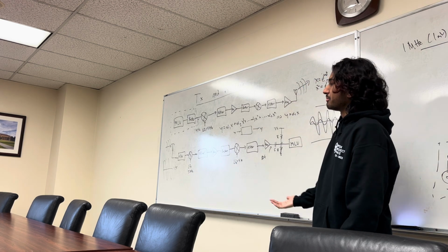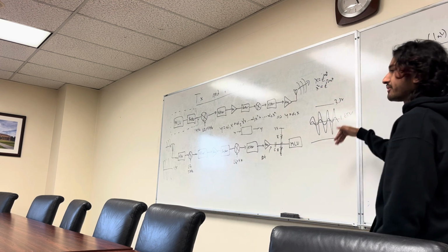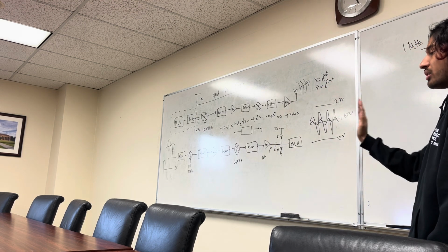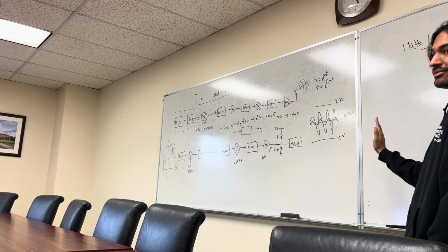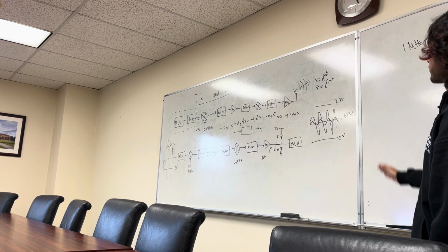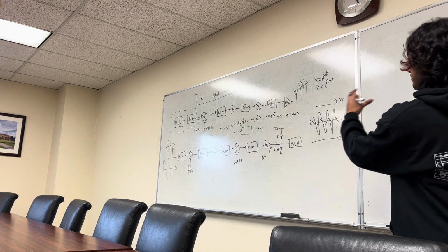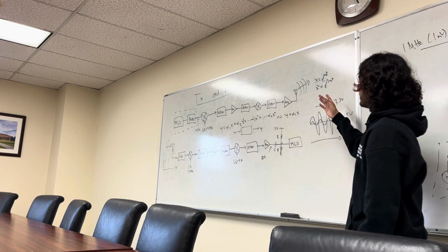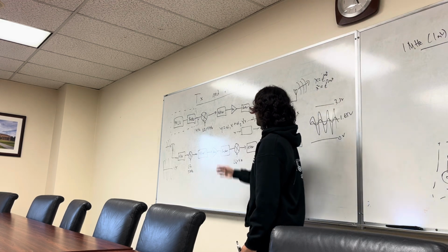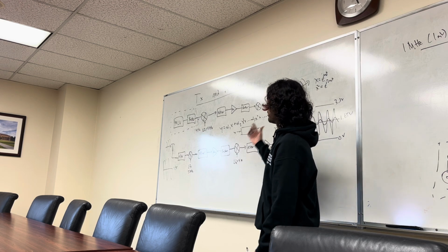For a mixer, this is problematic, right? Because for 1 megahertz, we saw that we're going to get 3 and 5, then we're going to get 1 mixed with the second harmonic of your LO, then the third harmonic. You're also going to have intermixing. So just from 1 megahertz going in, we have a lot of output spectrum across a very large bandwidth. Now, if this signal is large, we're going to have 1 megahertz, 2 megahertz, 3 megahertz, and so forth, going into our mixer.